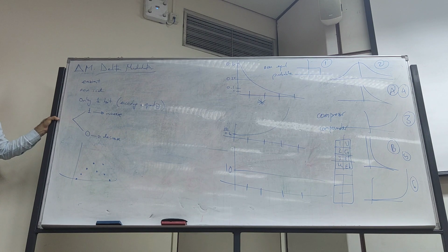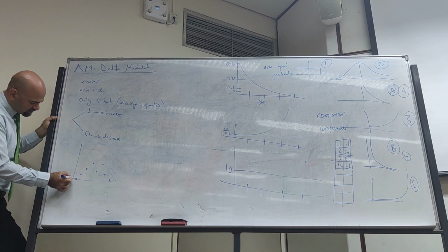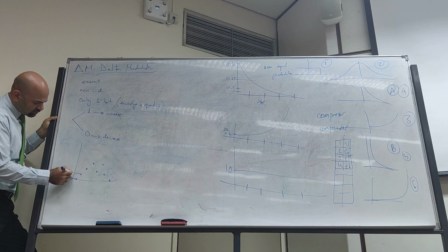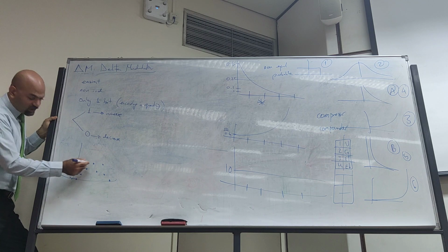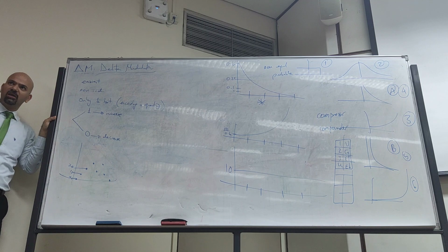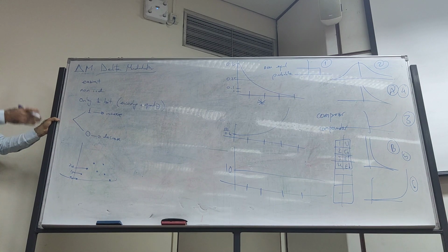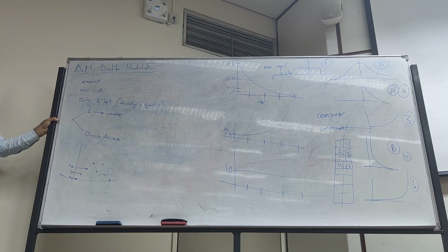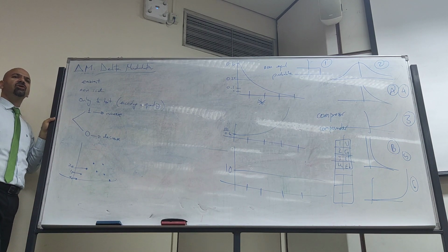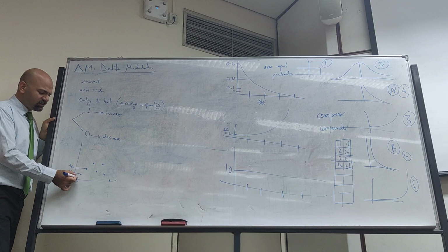If you do PCM, you have to check what the value is: this is 0.1, 1.5, 2.7, and so on. You have to do the whole procedure we have learned, and you send each one of them separately. But with delta modulation, they said, okay, we have an easier approach. What is that easier approach? Just tell me if it is increasing or decreasing. So I will give you the first one.